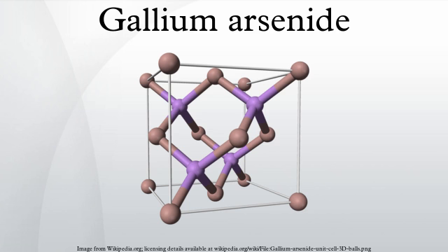arsenic antisite defects. The electronic properties of these defects cause the Fermi level to be pinned near the center of the bandgap, so that this GaAs crystal has very low concentration of electrons and holes. This low carrier concentration is similar to an intrinsic crystal, but much easier to achieve in practice. These crystals are called semi-insulating, reflecting their high resistivity of 10^7 to 10^9 Ω·cm.